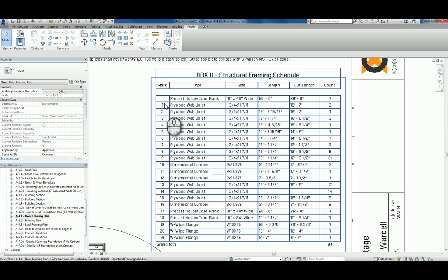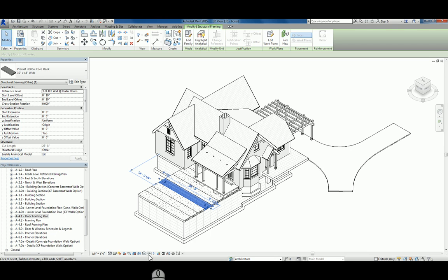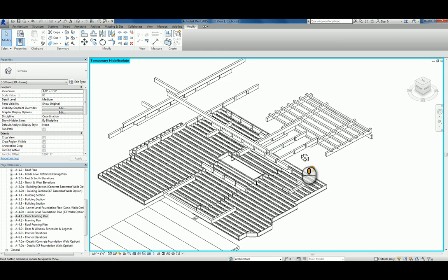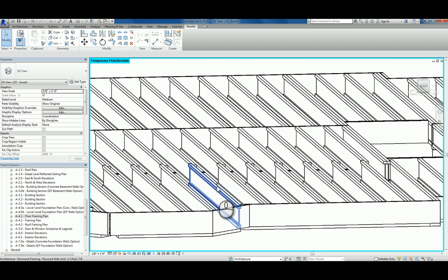So instead of my building model having, let me come down here, I'm going to isolate the category here. Instead of the building model having just a floor that was put in there, in lieu of the floor, I actually went in and put in all the beams, Revit beams, in this case I-joists, so that we could then do that takeoff.